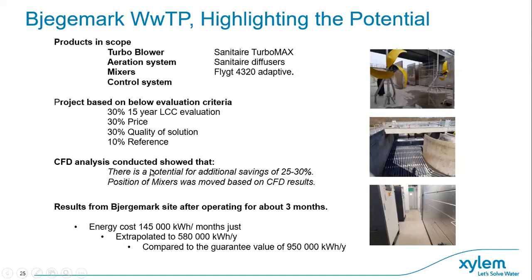We conducted CFD analysis, and it showed that there is a big potential for savings of 25 to 30%, and it also helped us move mixers to the right positions, because we saw that there could be some issues with the mixers due to air plumes coming into the propellers in this design.